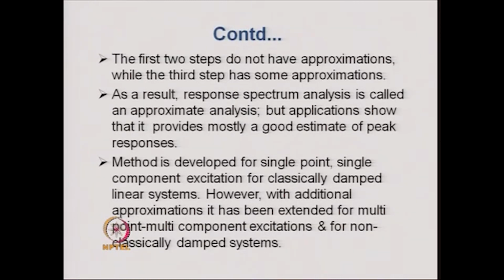While in the third step, when we are combining the maximum responses in different modes of vibration, we make some kind of approximations. As a result, the response spectrum analysis is called an approximate analysis, but applications show that it provides mostly a good estimate of peak responses.